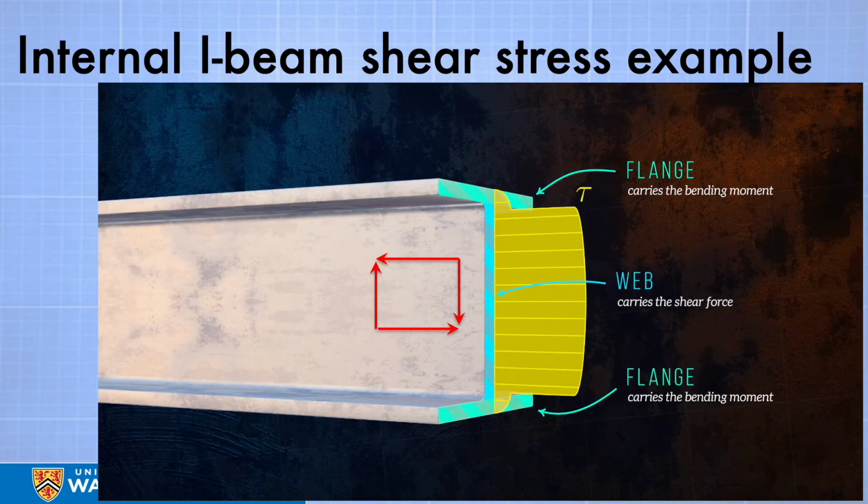Now, for every vertical shear force, let's say perpendicular to the neutral axis, creating a shear stress, there must be a balancing shear stress along the length of the element. This is something we often don't give enough consideration to, but we use shear flow to describe how the shear is accumulated over the height of the element. This is a great image here from the Efficient Engineer, a website I highly recommend, where they have some good visualizations of how stress is transferred across different types of elements.